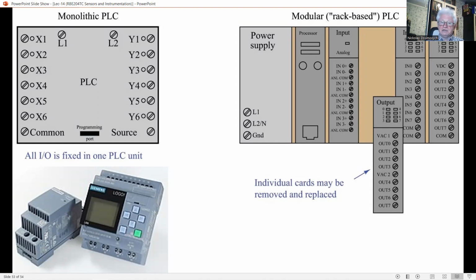Conversion between binary and binary coded decimal might be required for displaying digits on an LED panel and for interfacing the PLC with other digital hardware. For example, a PLC can be programmed to make a temperature measurement and a load measurement, display them on an LED panel, make some computations on these input values, and provide a warning signal or output depending on the result.